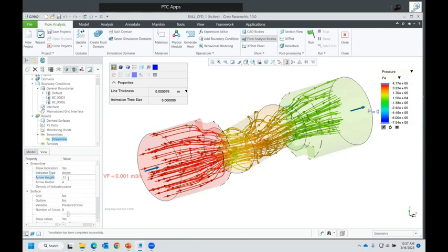I can make these arrows longer or shorter. Here, I can make it like 20. You can see it's a little longer, back to like maybe 4, so larger or smaller. And then you can define the density of them. How many do you want along the curve? Normal, coarse, fine, how many arrows do you want? Default is coarse.